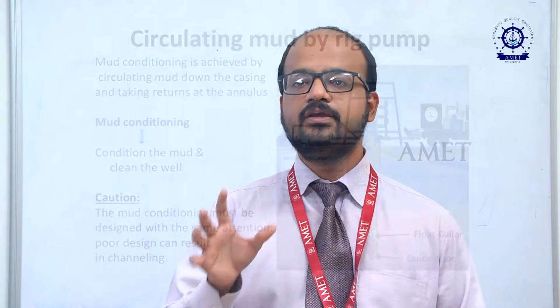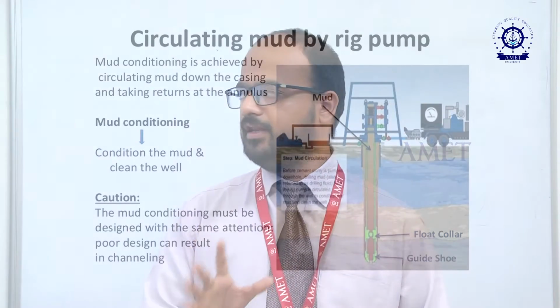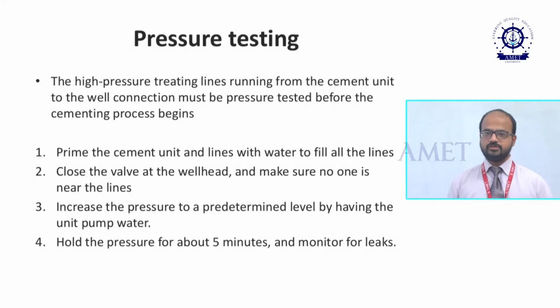What I have to do is completely fill with drilling fluid. The drilling fluid which becomes the mud cake, the same drilling fluid I am going to fill the well with. Once it is done, that is called mud conditioning. Now this is step 3.